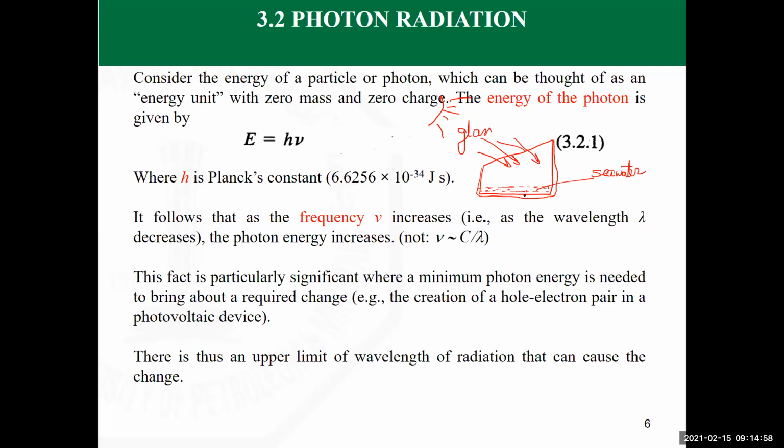As it gets heated, it transfers the heat by convection to the water. The water will get heated. The water itself can absorb part of the radiation and get heated. So evaporation is going to start. Some water vapor is going to rise up here. Water vapor is pure. This is salty water, but the vapor does not have any salt. So the water vapor is going to rise up until it falls into the glass.